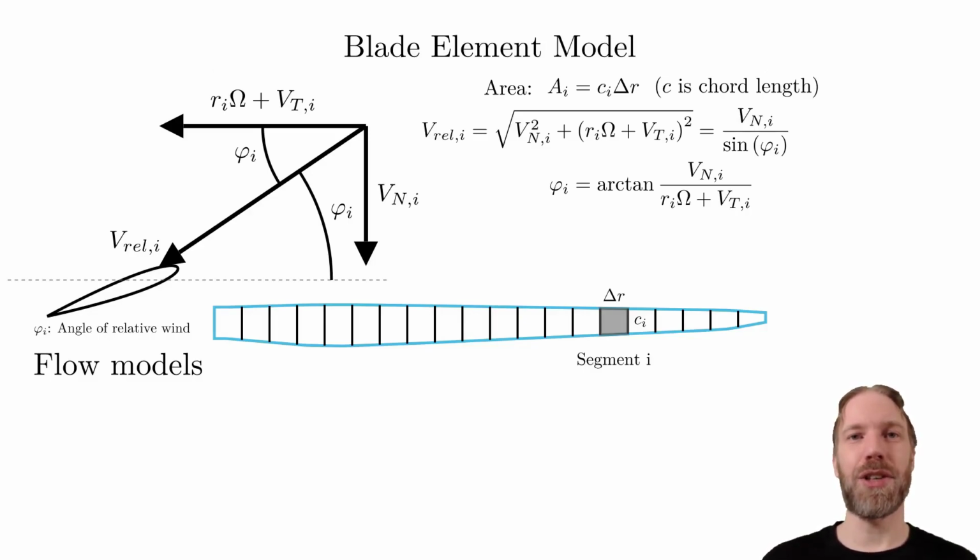The first is to use computational fluid dynamics and solve the full velocity field using a computer. The advantage is that one can handle complex flows, include terrain, see how turbines interact, and much more. The disadvantage is that it's computationally expensive.